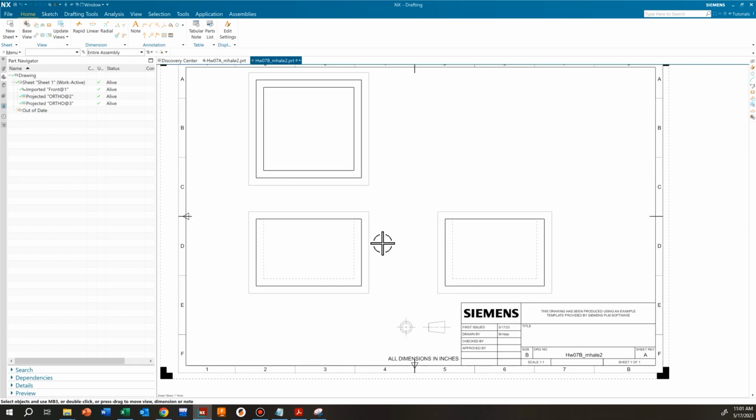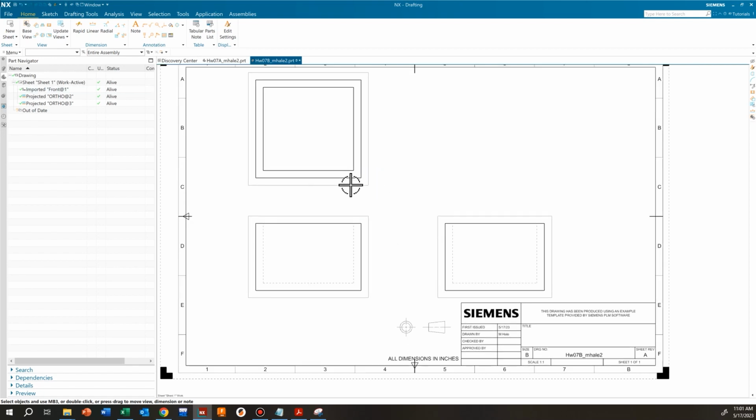So we can go ahead and add our dimensions for the box. And the way that we do that is if you come up to the top left of this middle box here, we have dimension. So there's lots of ways that we can dimension things. Sometimes we need to actually select an angle, or we want to make sure that we are using a radius or diameter.